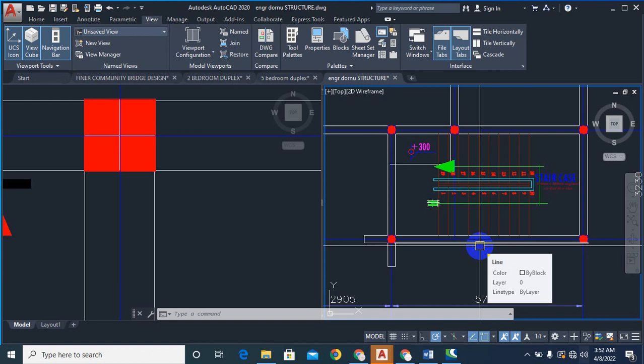10 meters, the depth of your beam will increase as well, because there are some designs where from the architectural drawing, they do not want any obstruction, most especially when you are designing for a mosque or a church in the middle, when they are not using a steel roof. Most times where you have larger span, they do not really want columns within the span. So in that case, the depth of your beam can be very high. You may be having up to 1 meter depth of beam. It depends on the span. There are cases you have even over 1 meter depth of beam. So the span will determine the depth of your beam.